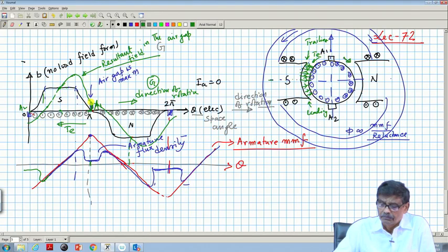and therefore, there may be an induced voltage loss, that is phi no load and phi loaded condition, the flux per pole will be slightly lesser. It can be taken into account by some factor, maybe 5% flux loss takes place for a large value of armature current.